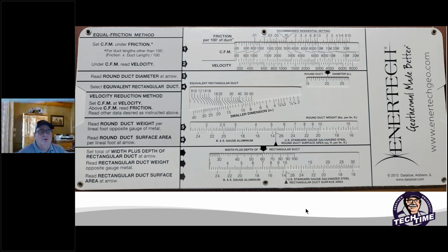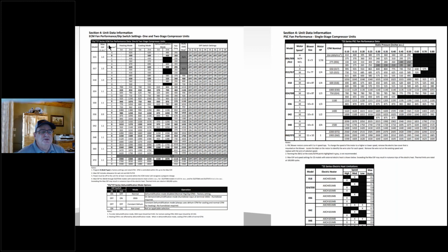In your manuals, which is kind of interesting, maybe a lot of people don't realize and don't read your manuals, but we have listings here for maximum external static pressure. Now this is for an ECM fan. Now the ECM fans are designed to maintain a certain amount of CFM, and they can ramp up and slow down accordingly to duct. But if you make that thing run faster because of high static pressure, more electrical operation is consumed versus doing it the right way.